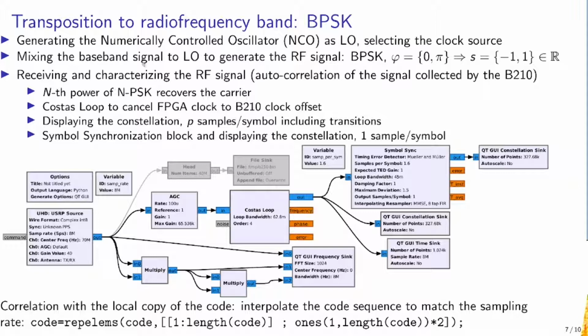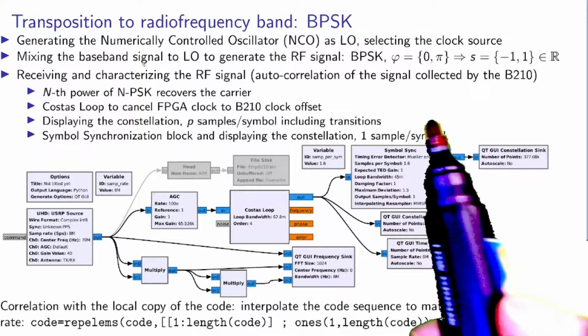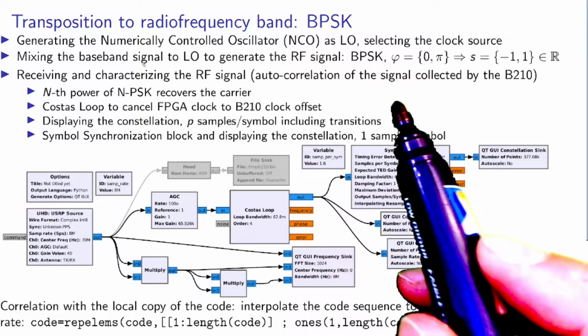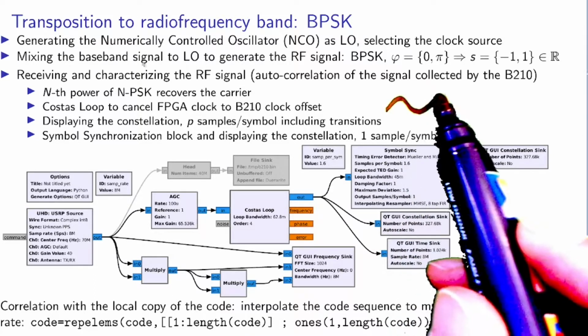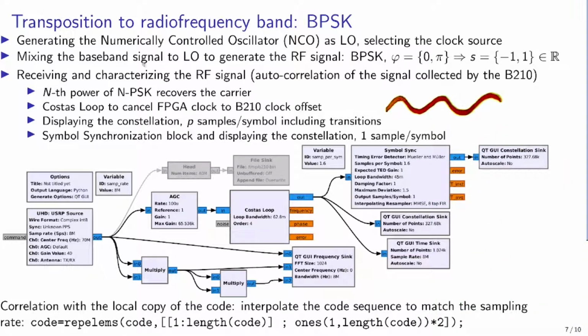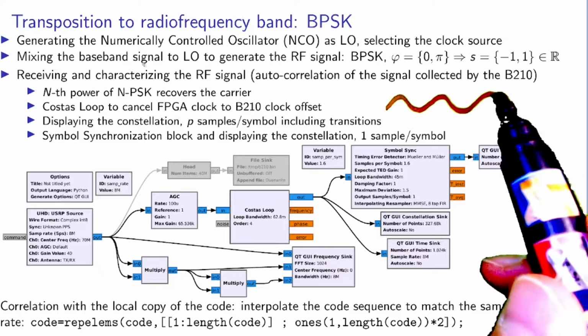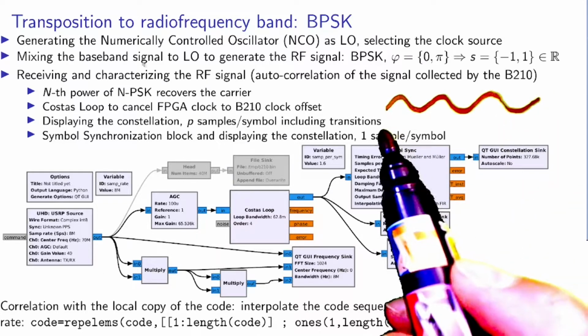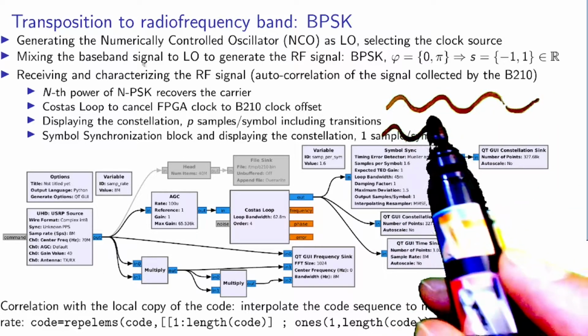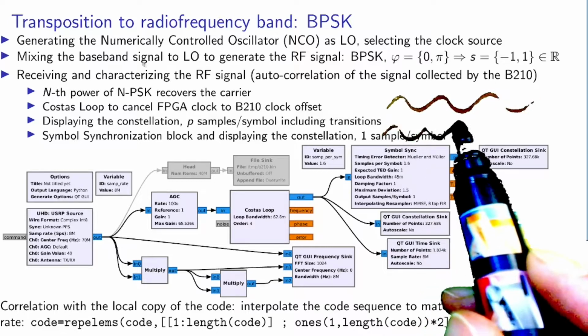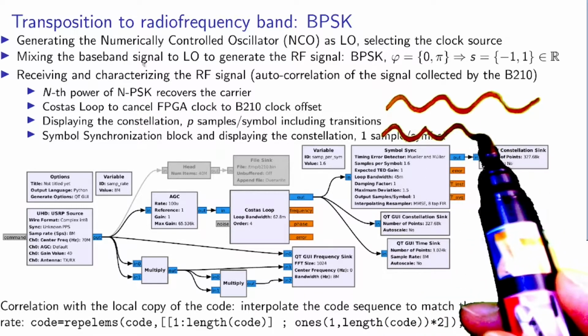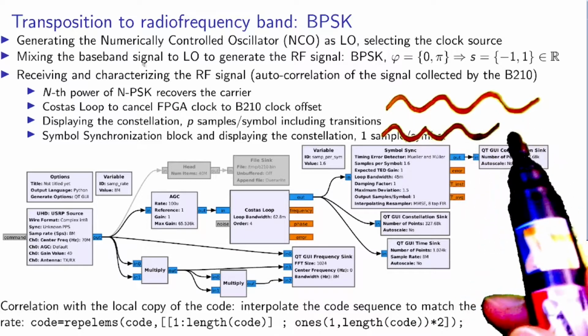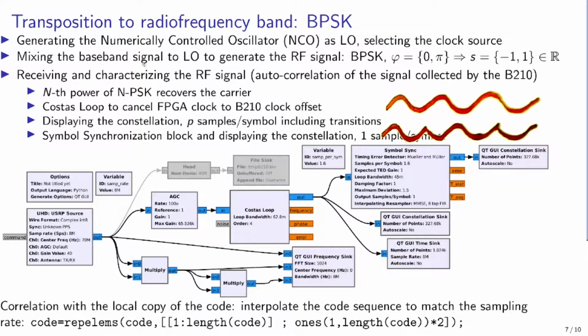So binary phase shift keying, BPSK, is based on the idea that we transmit a carrier frequency, a sine wave, and this carrier frequency needs to carry some sort of information. An easy way of implementing phase modulation is to say this carrier frequency will be phase shifted. So sometimes we change the phase. In this case, for example, we change the phase to the opposite shape. And for example, at some point, we restart taking the same phase as before.